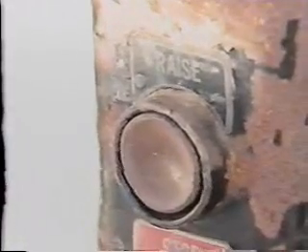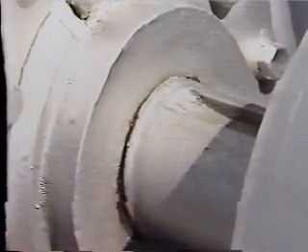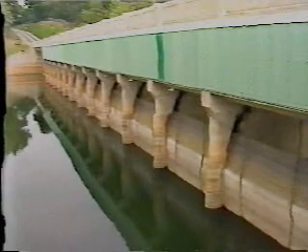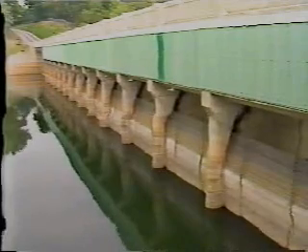Test the brakes by having operating personnel stop the gate midway up. Leave the gate in this position for about 20 minutes. Then check the gate again to see if it's moved. The gate should stop automatically when it reaches the raised position. Check the limit switches while in the raised position too, by having operating personnel try to open the gate further. If the gate doesn't move, the limit switches are set properly and working. If possible, try also to test operate the gate under maximum reservoir head conditions at a later date.